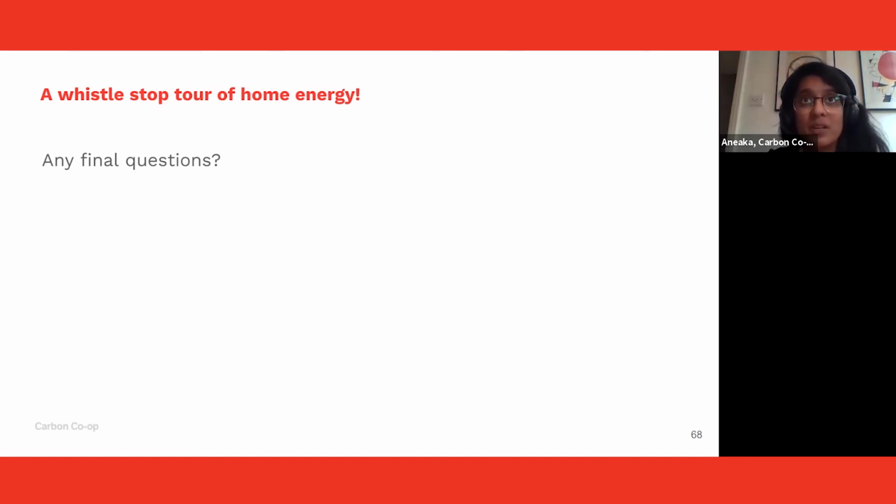You can get them from most DIY shops or online. They tell you what the relative humidity is, so you can make sure yourself that you're keeping it between 40 and 65. And if it goes above 70, think about why that is. So that's one important reason to ventilate the house well, to get rid of the excess moisture.